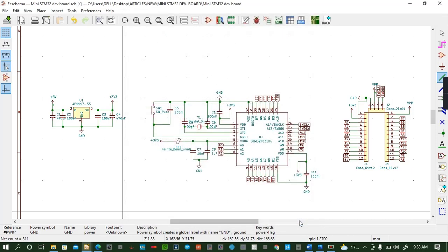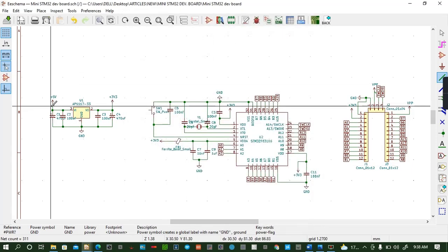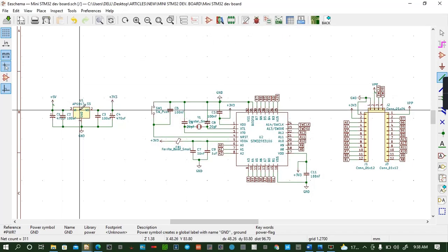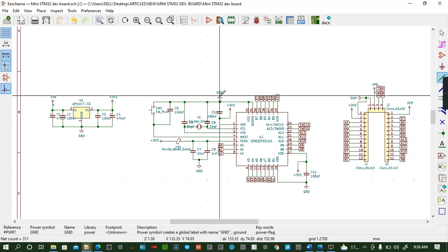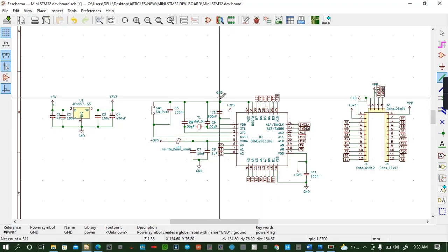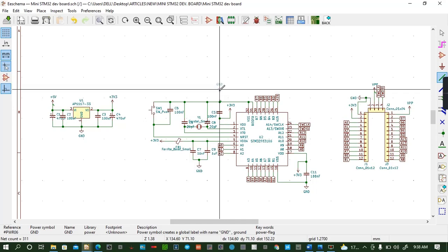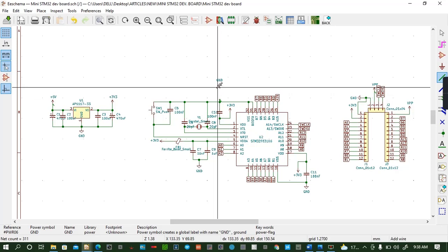And to end those warnings, you see here we don't have where the power is coming from. That's why you are being questioned there. So we know what to do with that one. Again, this one is ground. Okay, I can move this one. Move. We see whether the error will persist. Wire. We add the wire there.